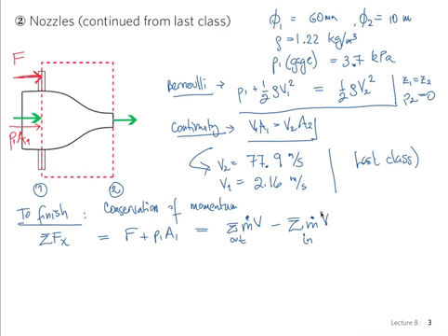So in the momentum going in, we have velocity pointing in, yet the outward normal is pointing out, and so that's a minus sign. And on the other side, on section 2, we have velocity and the outward facing normal in the same direction, so that's a positive sign here. Make sense to everyone? Good.